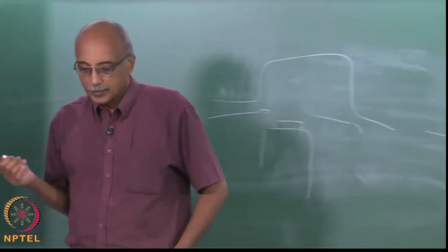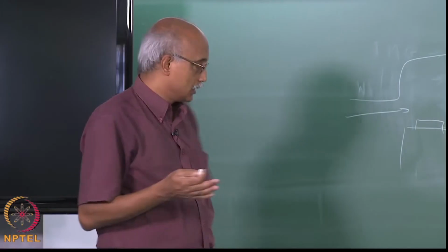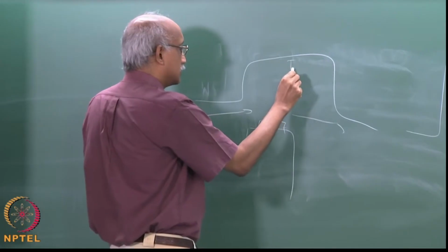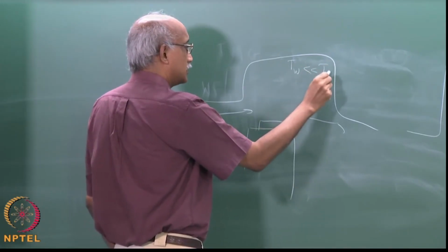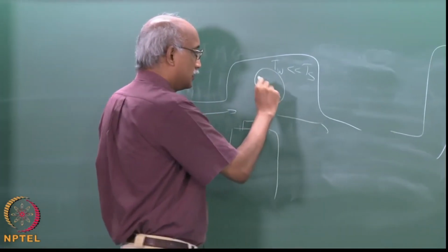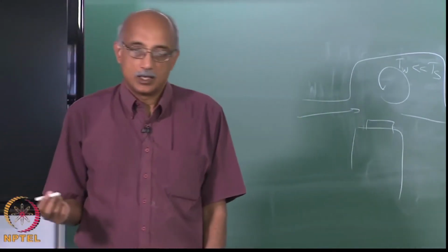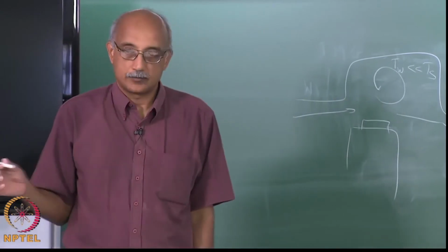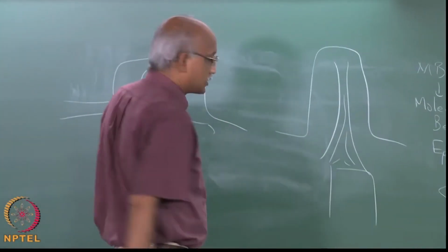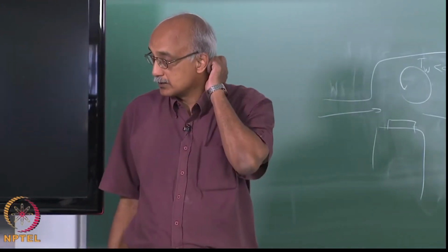Now, the reason that people prefer the stagnation flow reactor for MOCVD is that when you have the horizontal flow and you have a cold wall, so that TW is much less than TS, as we have said before, you can start setting up recirculation cells which can introduce turbulence into your system and prevent the formation of a uniform film.